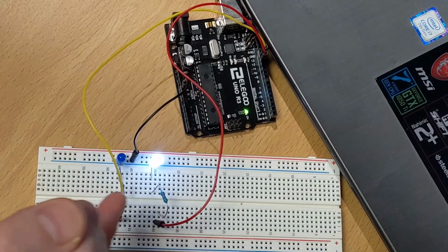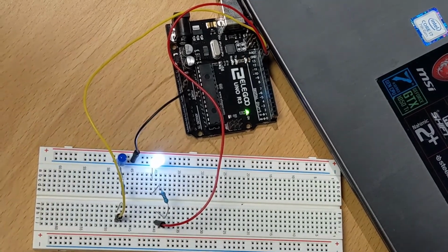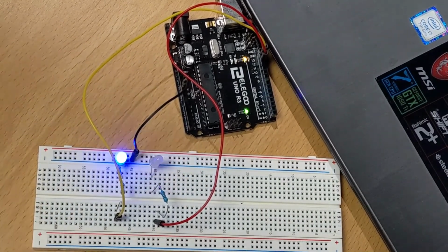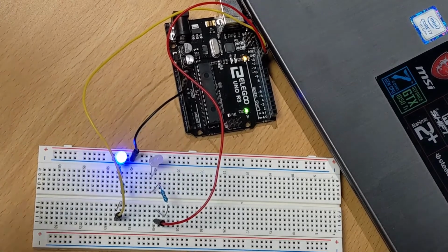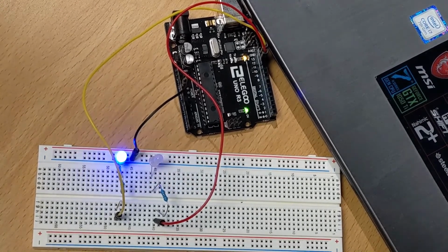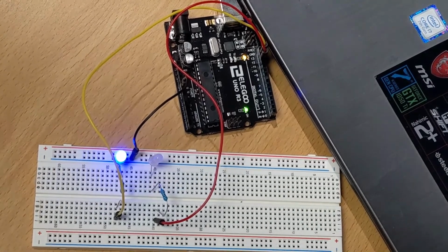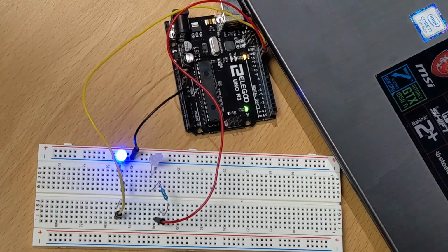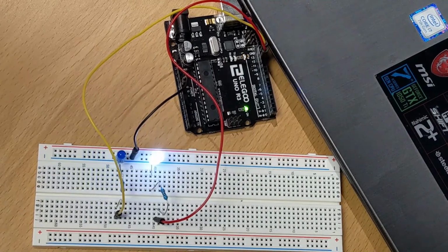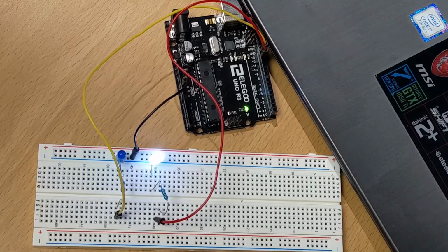So we change these two components for a much higher ohm resistor. So currently, these are what, 200? Yep, 220. So if we increased it to, say, 400, we can make both LEDs dimmer because we'd be slowing the current down with an increased resistance. Well, what we could do is replace it with a variable resistor, which is the one with a dial on, like we change the volume and things like that, or a dimmer like we'd have on a switch at home, and that would change that we could vary the amount of resistance.